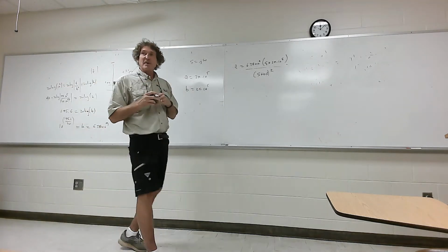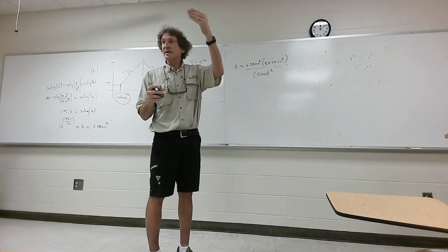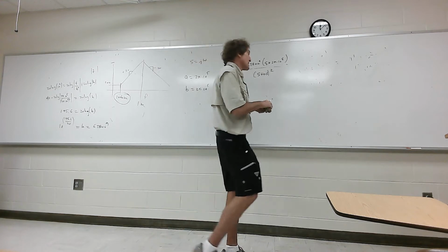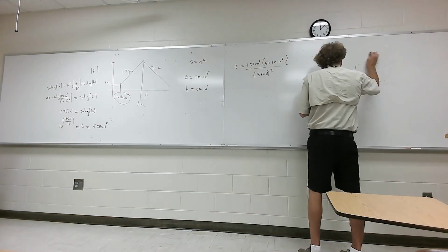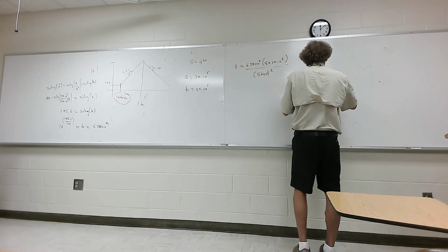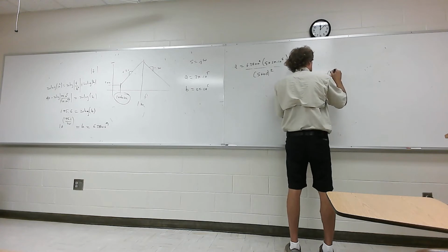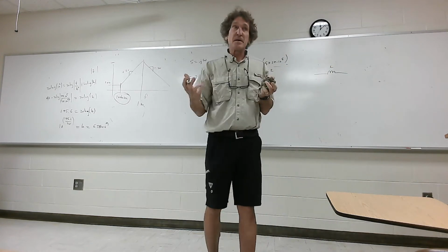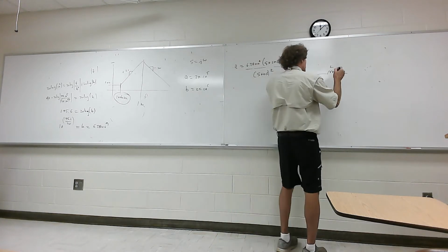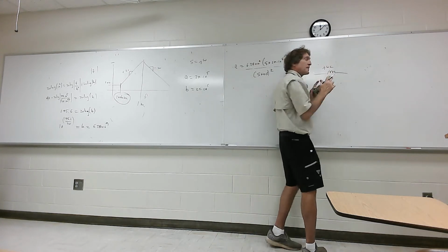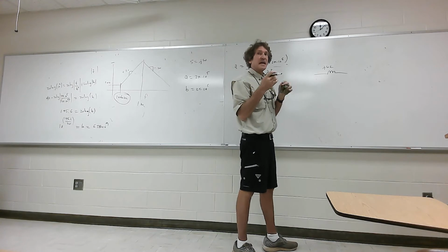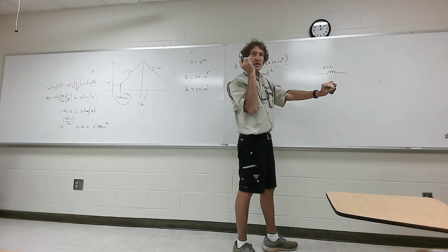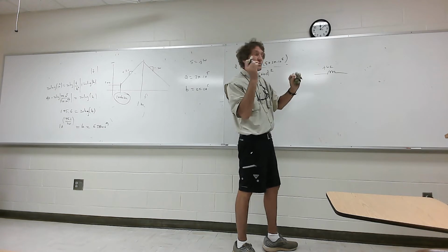So if you want the values, here's where I'm going to go back now. I didn't complete the inductor model. Remember last time I did the capacitor and the resistor. For an inductor, at low frequencies, an inductor looks like an inductor. Makes sense. The impedance of this would be j omega L. But there's one thing you can't get away from, that there's an inherent amount of resistance to the wire. Even at DC, it may be very small, but some.